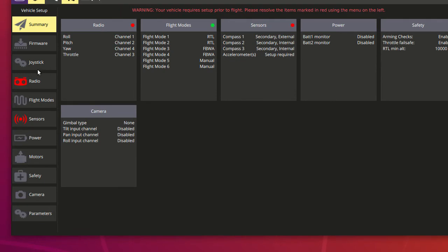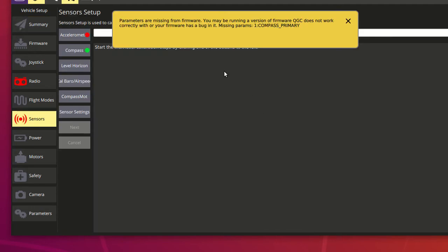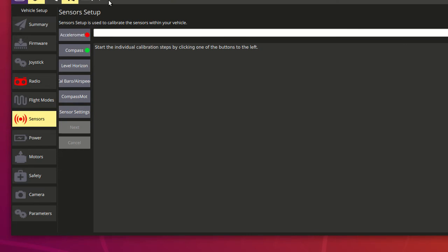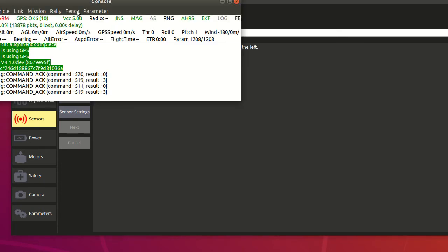But you see we can't use it because there are some red items here, such as sensor calibration, radio calibration, accelerometer calibration. Seems crazy because there is no accelerometer here to calibrate. It says rotate the vehicle. It sounds crazy, but right now we have to fool the ArduPilot pre-flight checks. We should change the parameters for calibration to make it think that it is calibrated, or do a very simple process. Come to MAVProxy, parameters, load. We will give it a default parameter so there won't be any pre-flight check error.